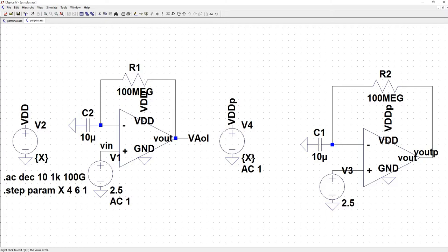Oh, I'm stepping. Oh, okay. So I'm making the mistake of stepping. Oh no, but I should be. I should be stepping VDD, the same as this VDD, but with the AC source applied. Okay, so that's why it's going to take a little bit more time. So I'll just go ahead and run it again, and then I'll cut you guys to the end of this.